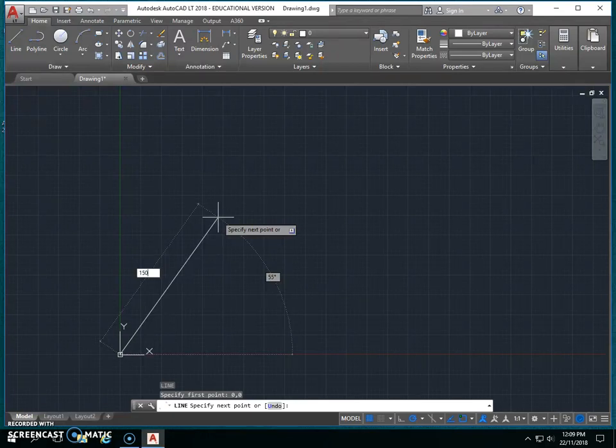And because a Warren truss has equilateral triangles, what angle do I want to be at? 60. So when I do that, to type in the angle, I have to use the less than sign. So I type in 150 less than. Now, to get a less than sign, I press shift comma. Can you see that? Now it's measuring 60.